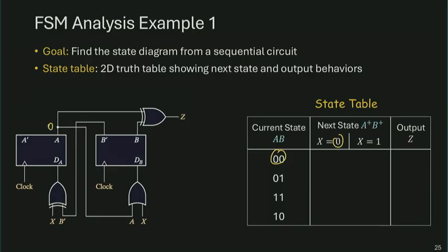I'm going to plug in those values into my circuit. So these are all zeros. These are all zeros. All right. So for the OR gate, you have 2 inputs of 0. Each of them is a D flip-flop, and A and B are the corresponding flip-flop outputs. We typically call them D, but to differentiate them, we call them A and B. But really, those are the 2 Q outputs coming from the 2 D flip-flops. And these are D inputs: D input for A, D input for B. So the OR gate produces 0.